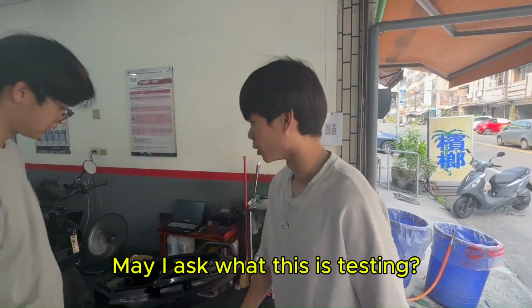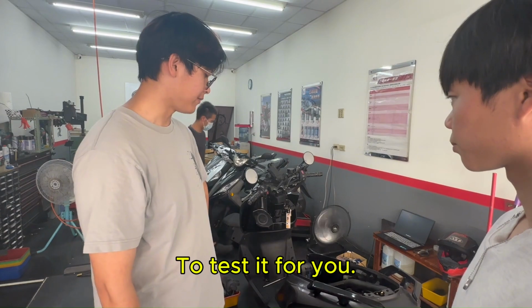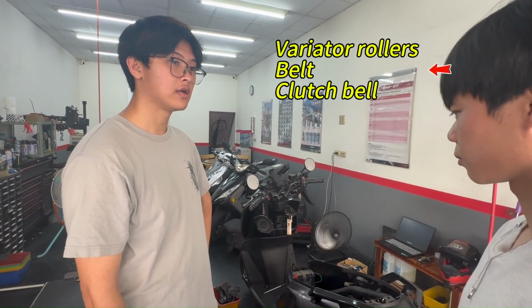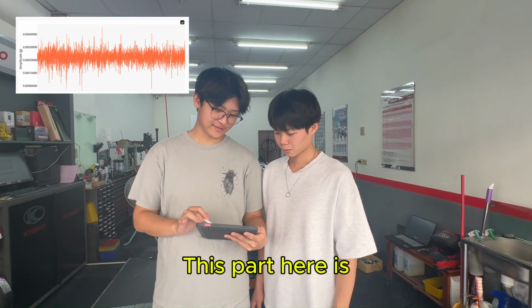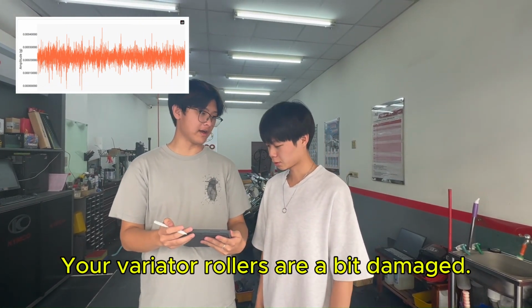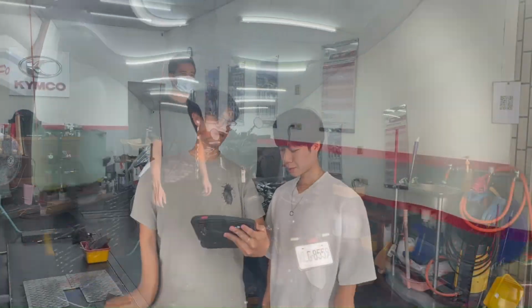May I ask what this is testing? Because you just said there is something wrong with your transmission, so we use vibration detection to test it for you: variator rollers, belt, clutch bell, whether there are any wear and tear issues such as these. Look at here, this part. We just checked, and your variator rollers are a bit damaged, so they need to be replaced. And here are some suggestions. You can take a closer look.